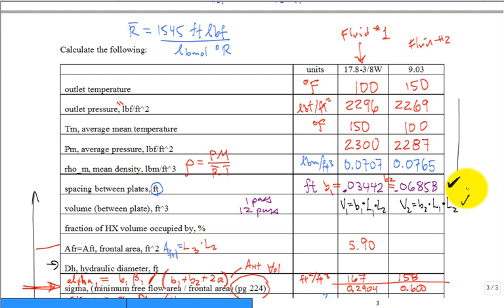What I computed was the fraction of the heat exchanger volume occupied by basically the passageway for fluid 1. I know it's finned, but it's 32.9%, and then 65.6%. And there's basically 1.6% occupied by the plates. So for the fluid occupying this wavy fin for passage 1, 33%, and it's about 67, 66%, about 2% for the plates. All right, how about the frontal?